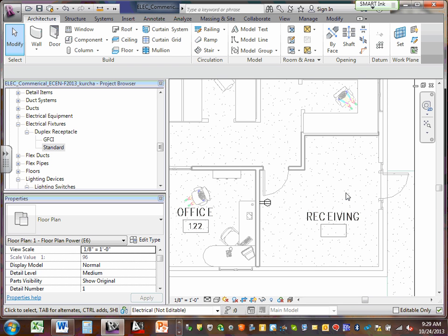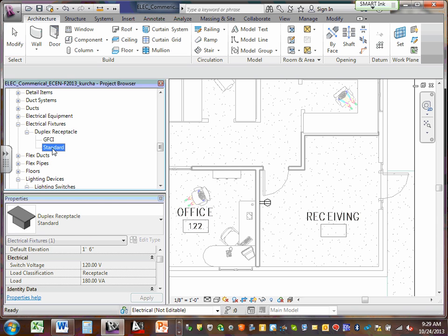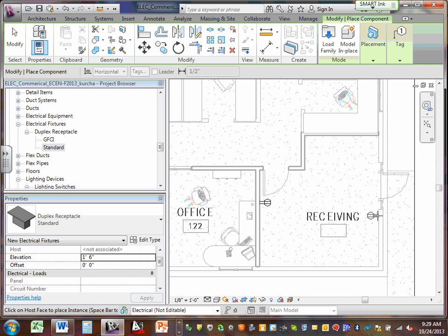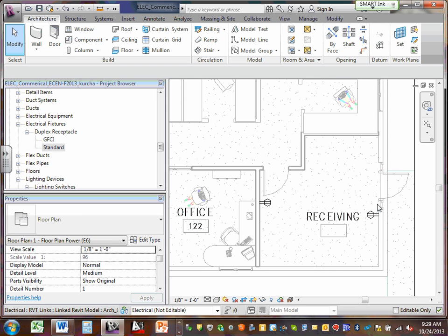Now, the requirement, guys, says one receptacle for every 1,000, so let's just follow the requirement. Some people might add another receptacle or what not. It says 1,000 for the receiving area. We don't need a whole lot. So be careful not to add more receptacles than asked for. But I want to make an executive order and add one more receptacle here. So I want to have two receptacles, one in this area and one in this area. Even though, how many did we need by the criteria? One. So be very careful adding more.